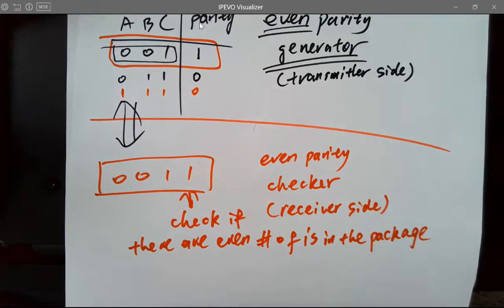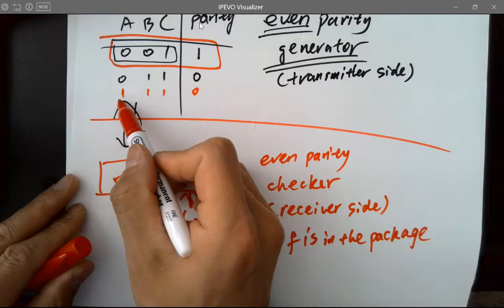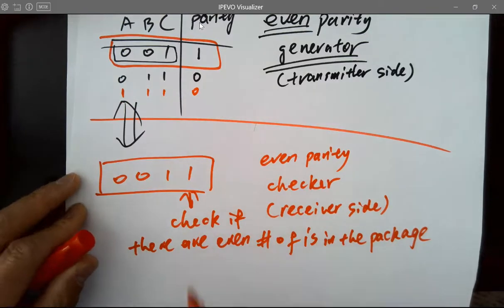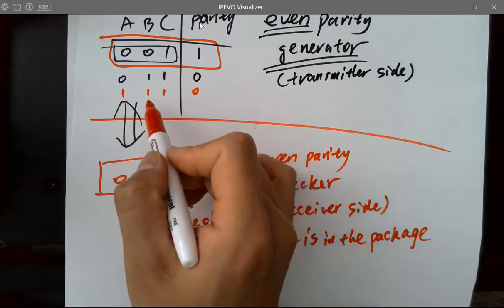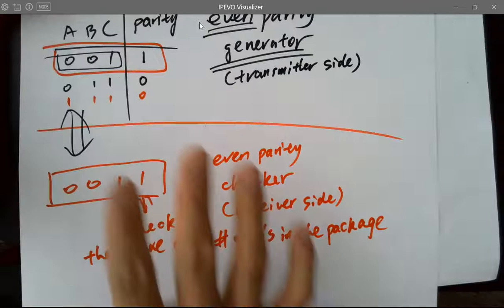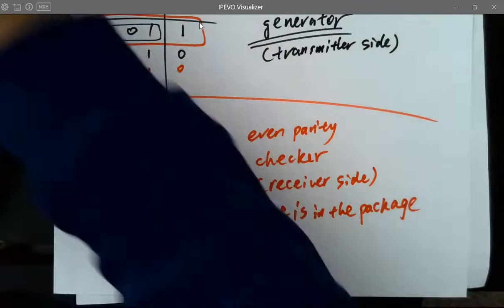All right, and eventually there are an odd number of ones being received by the receiver. So it's going to be able to tell that some of the data are being flipped because of the noise or become something else. And then it's going to drop that data, not store it into the register, just to not use it. That's how that works. So it's literally just a combinational logic block, and to implement it, you just need to convert that concept into a truth table.